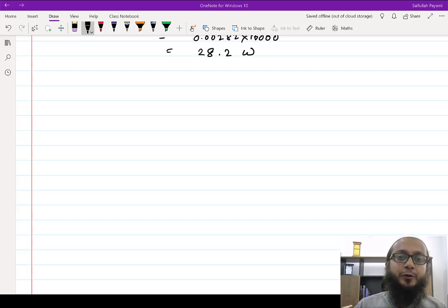So you have to convert the given per unit quantity to a new per unit quantity. Say you are connecting two transformers whose base voltages, series parameters and shunt branch parameters are all given in per unit, and the base voltages and apparent power of the two transformers are different.